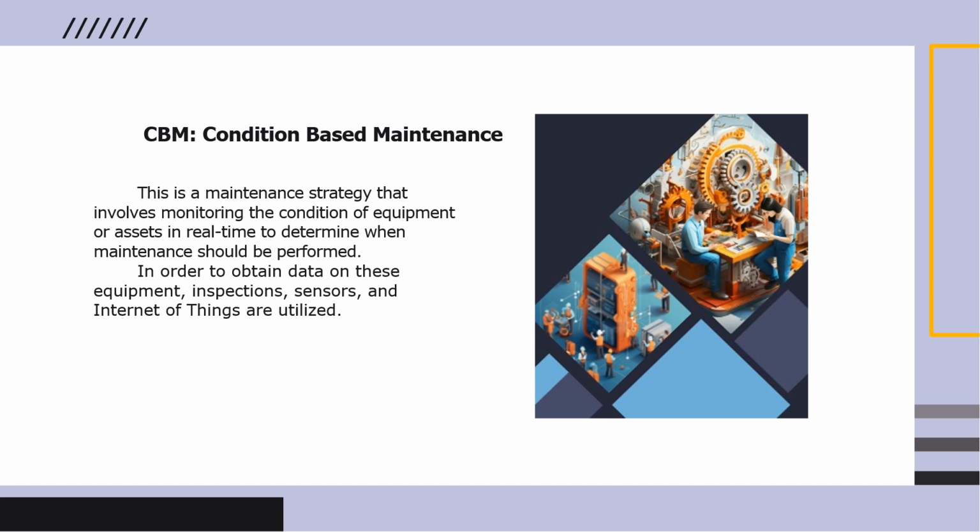So proactive maintenance is actually maintaining an equipment or a facility based on studies you have known that you're able to look into the future and understand that based on the condition of the facility or the equipment in a certain period of time in the future, it's likely to break down. So rather than allowing it to break down, you can actually carry out maintenance based on that condition that you have observed.